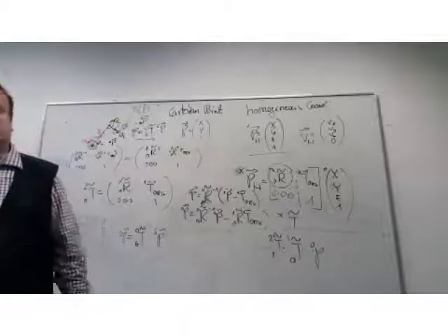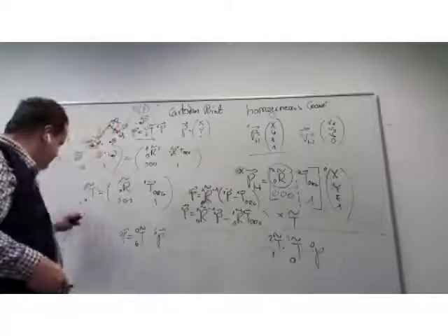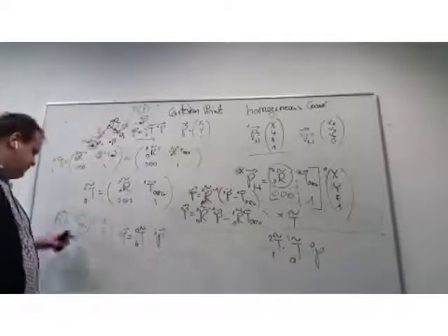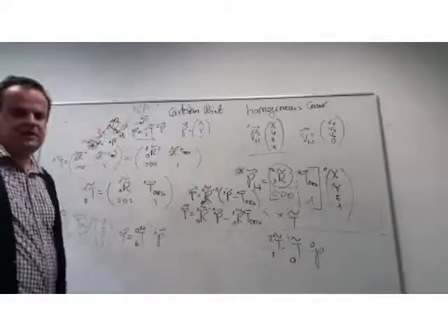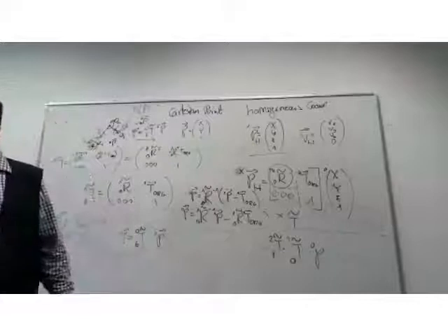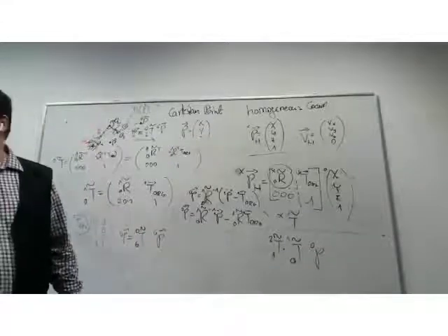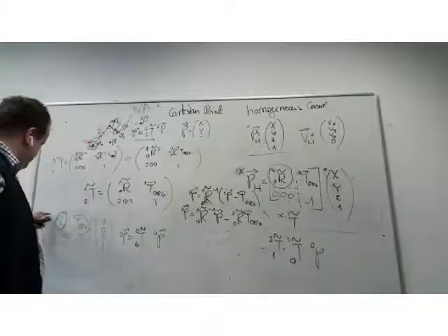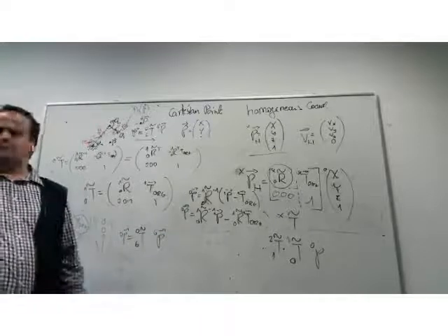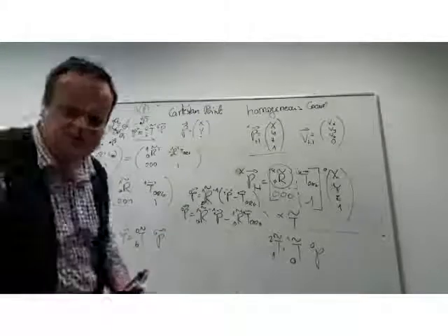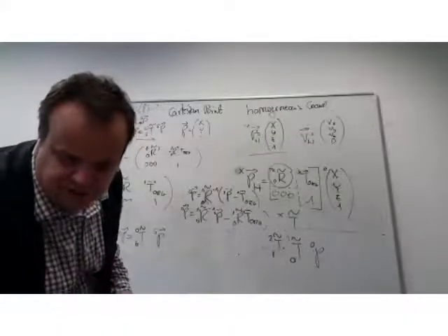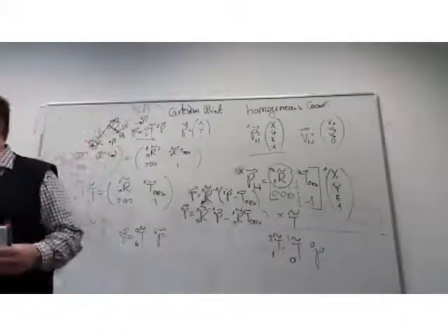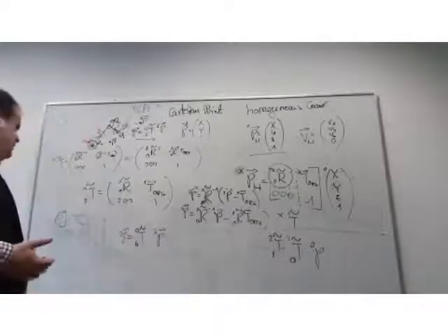So we can recover not only the forward kinematics in the translation, but we can also recover, for example, the yaw, pitch, roll representation directly from analyzing the matrix R of the translation. So we see that this allows us already to calculate forward kinematics, but